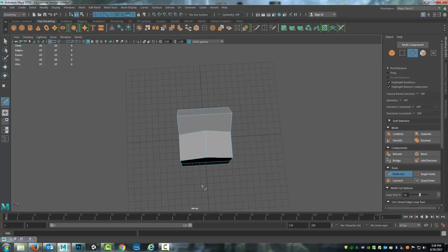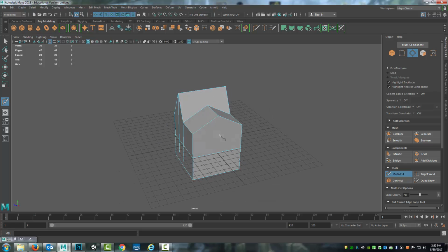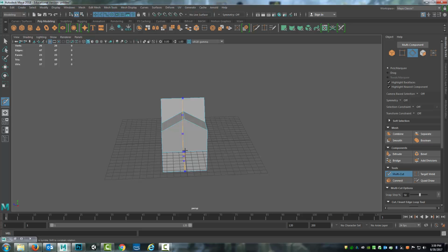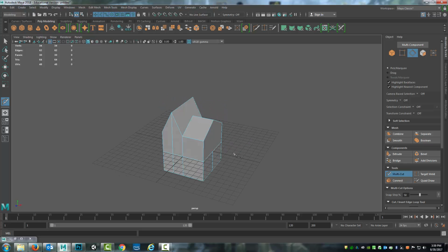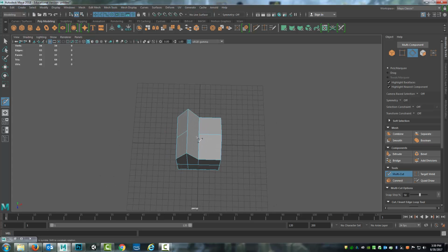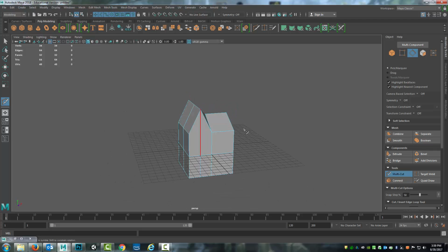Now I should be able to do the same thing through the form here, but I'm also going to show you another problem that's presenting itself. So I'm going to do the same thing where, because I know it's right in the center, I will hold down Shift and Control and left click to create that edge loop right at that snap step of 50%. I can then come here and cut up. I can also come here and cut down. And so now I've got a model that's got good topology, and it's highly efficient, and it's clean.